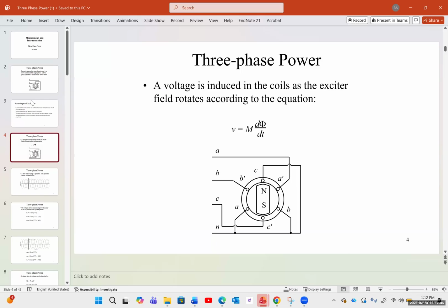Depending on your application, you may want to have a permanent magnet. This one has a permanent magnet, but you can even ditch that and use a solid coil like a squirrel cage system. And sometimes there's a trade-off on price and performance. If you use a permanent magnets uses rare earth material that are extremely expensive. So it's only beneficial when you want something very high performance with minimal loss.